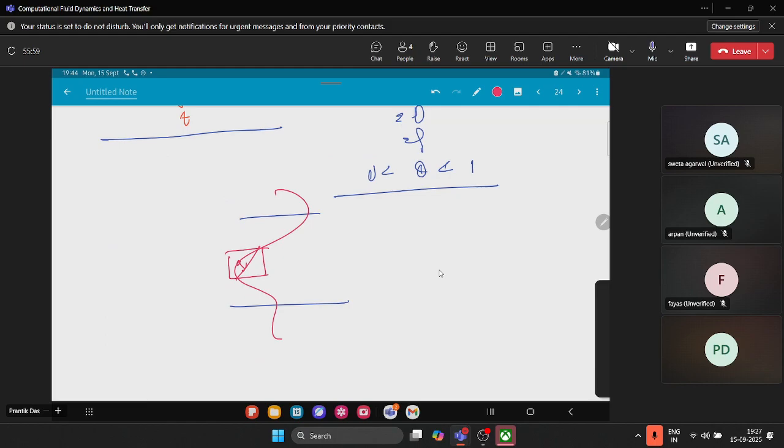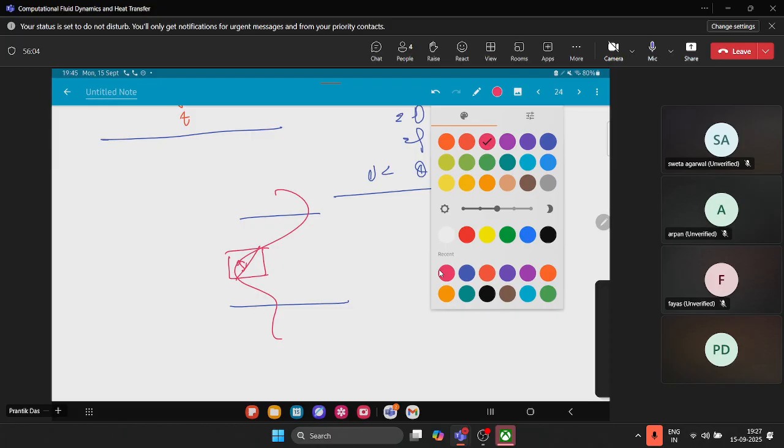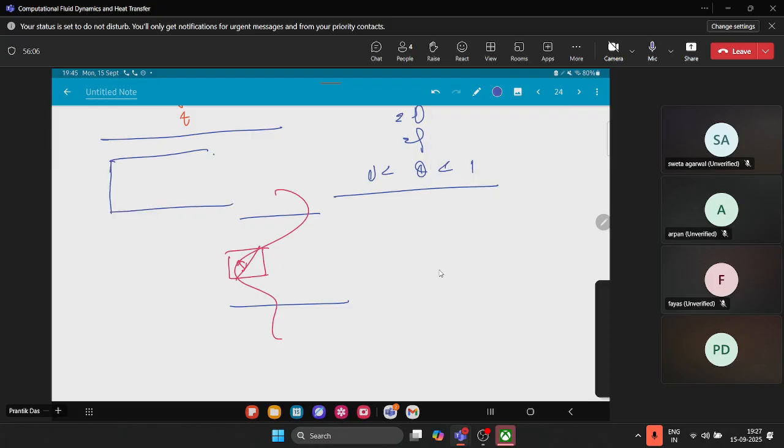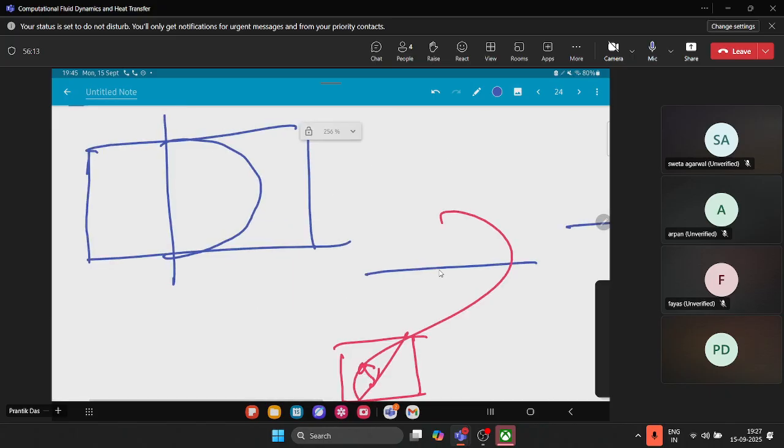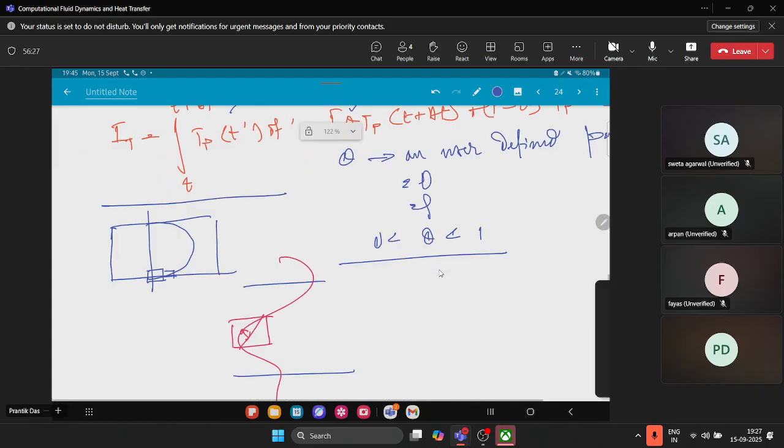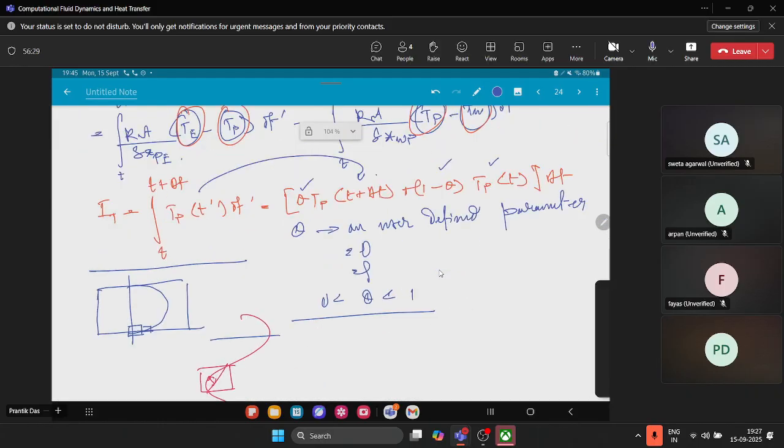That's why I always say that if it's a curvy thing, or in the near wall region where we have a parabolic profile for a laminar flow through a pipe itself, you use a wall function, or you use a higher accuracy discretization scheme, or you reduce the cell size and then you can use a low order discretization scheme. So many things can be done, but we take that thing into account. Okay, is it clear to you? Yes, sir.